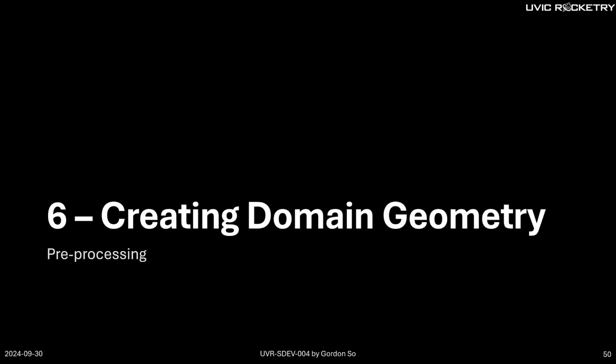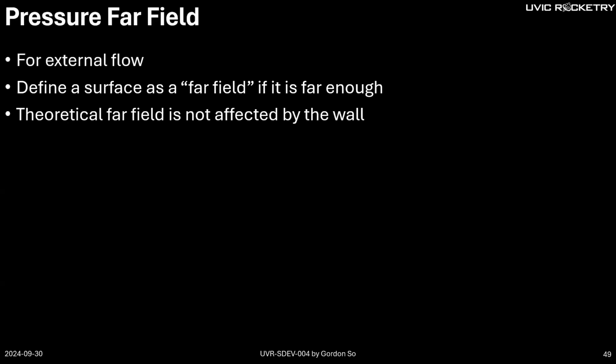Yes. For the far field, how do you know where to set up the far field before you've run the simulation and know where the far field needs to be? Yes, that's a good question, which we'll cover in meshing, because you don't really know until you run the CFD.